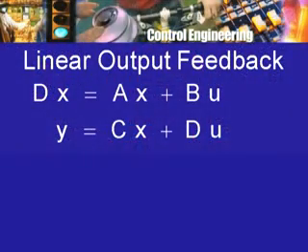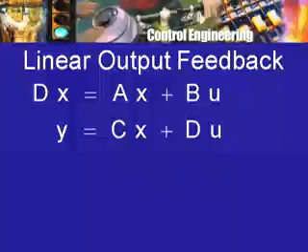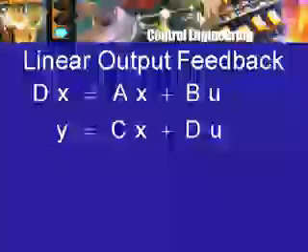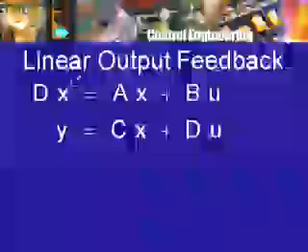but we will assume that we have available outputs. So, we go back to the equations, we have x dot equal to Ax plus Bu, and now I have to take cognizance of the output equation y equal to say Cx plus Du. Now, when I use feedback, I will use feedback which is based only on the output y rather than on the state x.